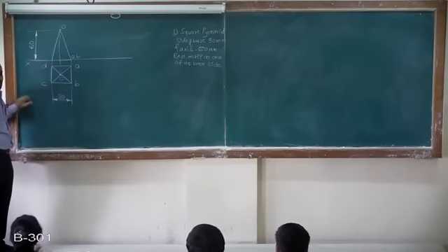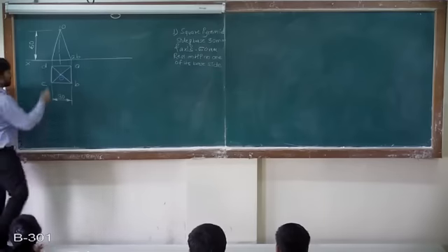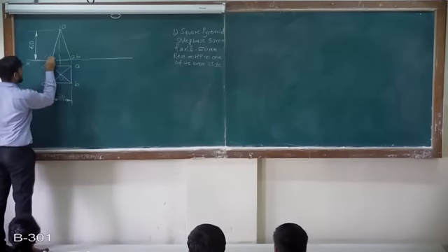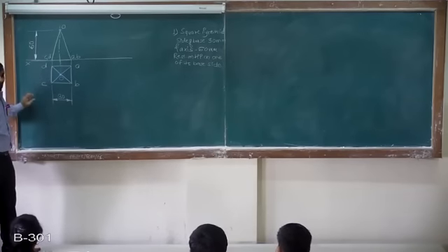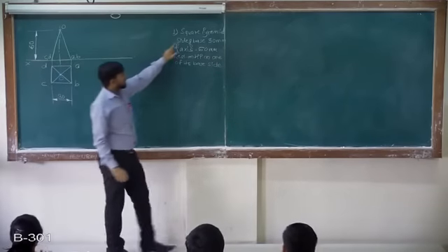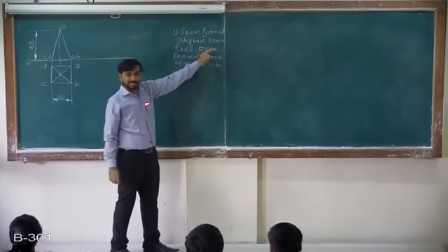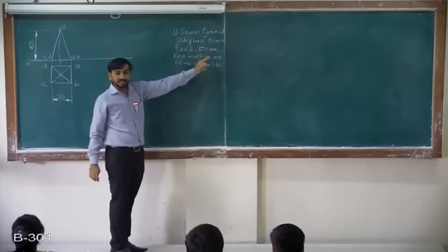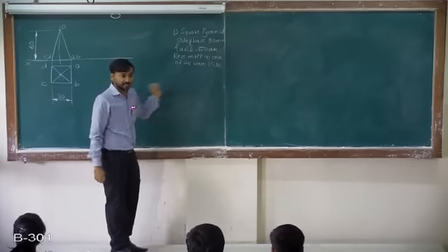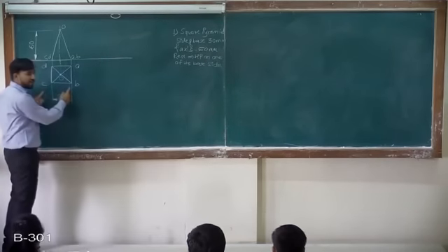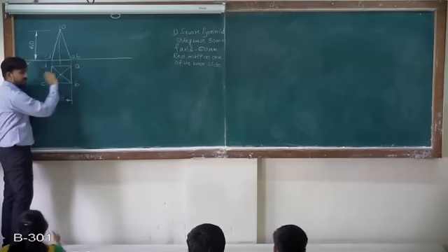So the resting side is AB on the right. This is CD, the opposite side. Now the first stage is done. So this is the given data: square pyramid, side of base 30 mm, axis 60 mm, rest on HP on one of its base sides. So I have drawn a square of side 30, with the side on the right.